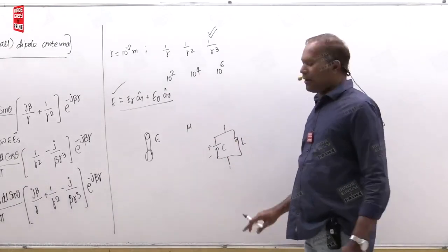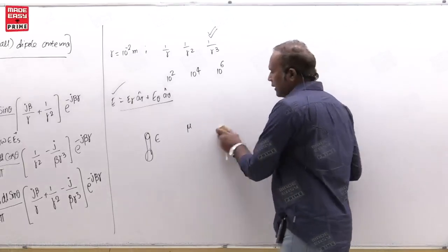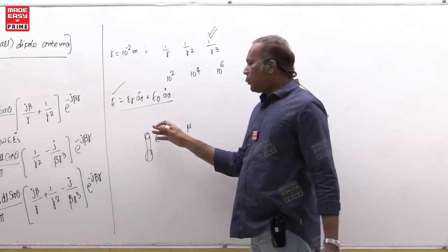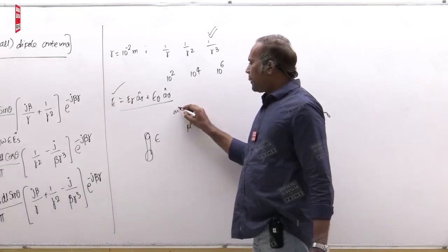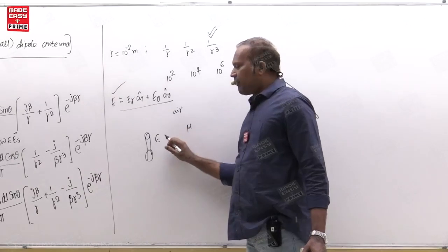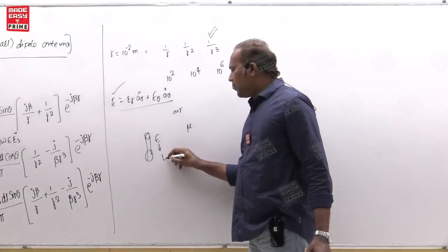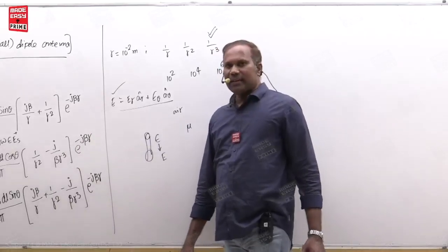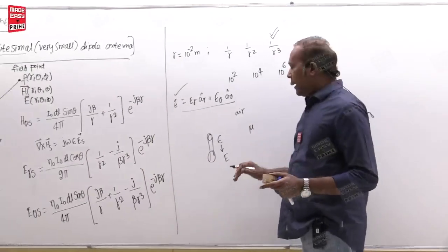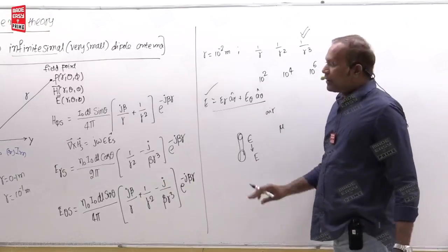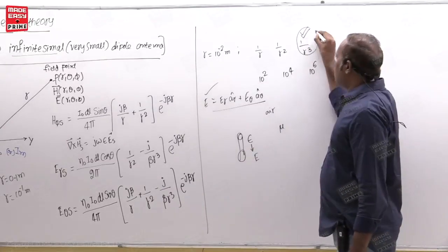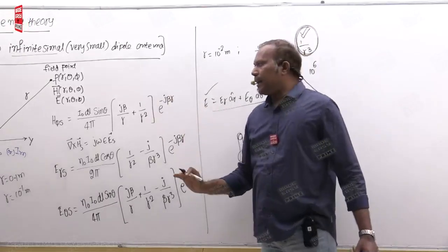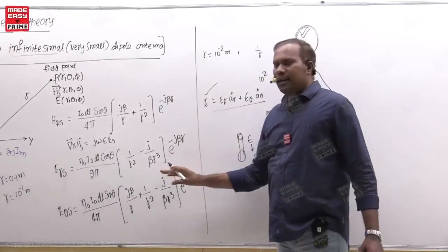Same way here also. First, there is energy in this conductor in the form of current that is ready to radiate. Now in the air medium, epsilon receives that energy first. If epsilon receives, it means only the electric field receives energy. That's what these equations are saying. So that is why at the beginning the magnetic field is not there. That is why this term has a very high value near the antenna. That means only the electric field is there.